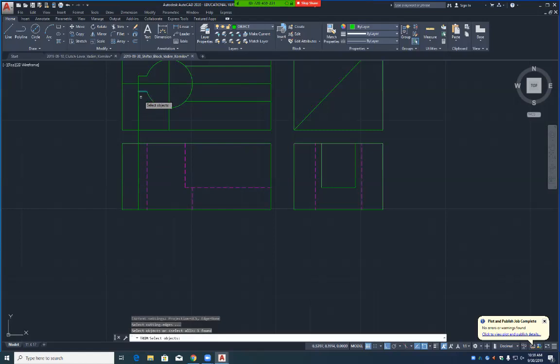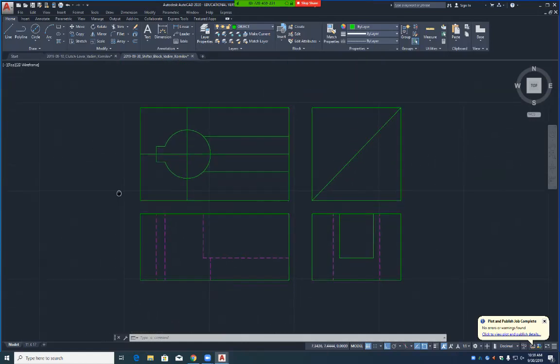Nice. And there's your line right there. Do you see what I'm saying? It's already the right length, isn't it? Automatically for you. The whole concept that you've got to get through is CAD, make it as simple as you possibly can. If you have a line, copy that line. If you have a from point and a to point, copy it. It's the right length and already on the right layer for you.